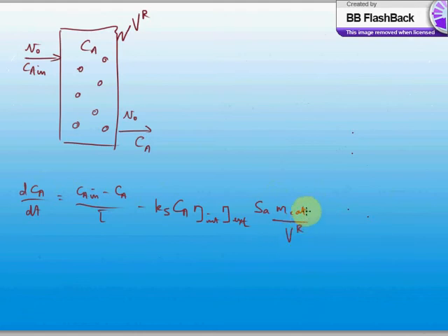And you can identify this as the bed density of catalyst particles, right? This is the mass of catalyst in the reactor. That's the volume of that reactor. So that's effectively the density of catalyst particles in that reactor. So anyway, let's just lump all these things together. Let's just group all of this as a set of constants. So let's just call all of that equal to K1.